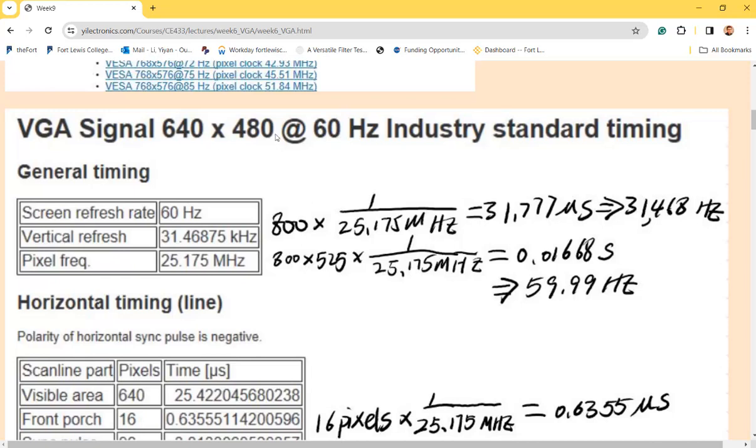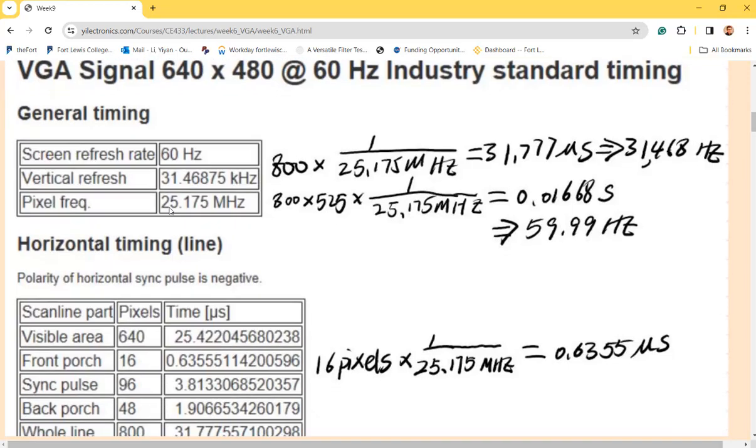It's just multiplied by this many number of pixels, right? 60 Hertz times the total number of pixels. So somewhere around 25 megahertz, that's the pixel refresh frequency. So you are assigning each pixel to the monitor at 25 megahertz, like placing pixels to the monitor at 25 megahertz. Okay.